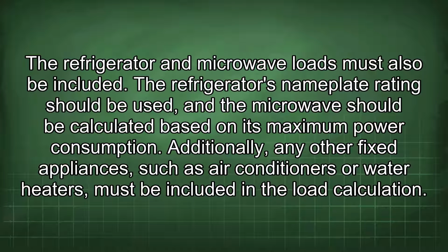The refrigerator and microwave loads must also be included. The refrigerator's nameplate rating should be used, and the microwave should be calculated based on its maximum power consumption. Additionally, any other fixed appliances, such as air conditioners or water heaters, must be included in the load calculation.